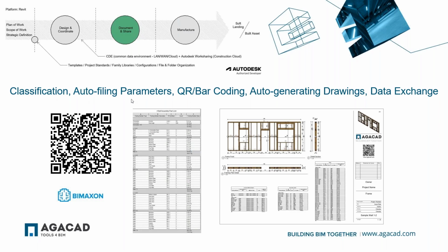Numbering and applying numbering conventions. So how you choose to name your studs, that's up to you. But once you know how you want to name things, you can do that with either built-in numbering functionality, or you can use sort mark. That would really allow you full access of filling parameter values that you're gonna come up with. So just kind of introducing the naming conventions and standards is quite straightforward.